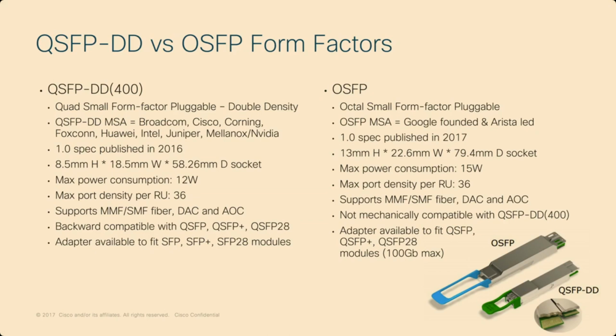It is physically smaller than a QSFP or QSFP-DD. And there are some drawbacks to it, unfortunately. There is a higher maximum power consumption spec on it, but in order to do so, you need to actually put heat sinks on the actual transceiver. And then in practicality, when you try to run that at high speed all the time, then you start running into some thermal concerns with the design for the switches. So we stuck with the QSFP-DD.